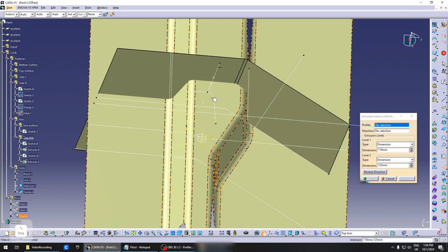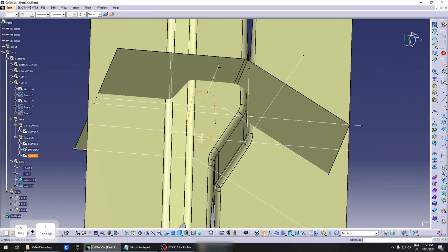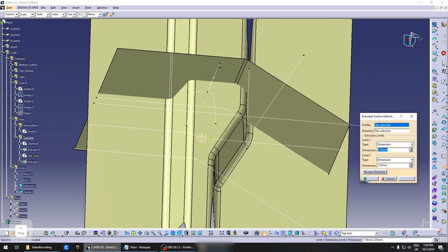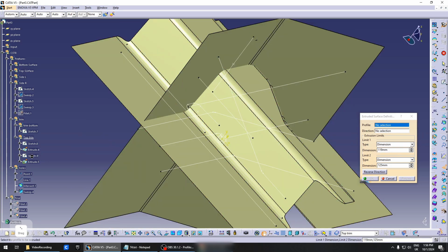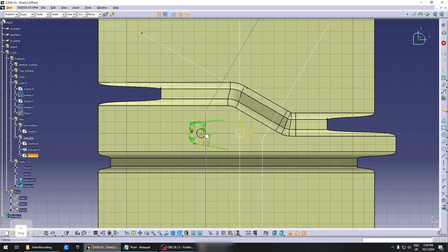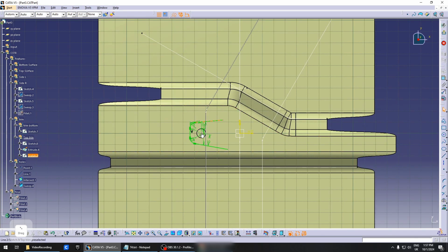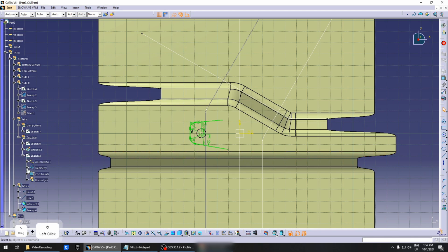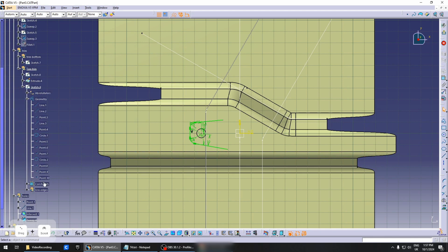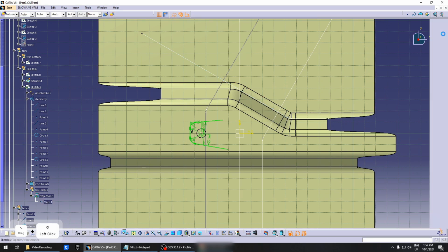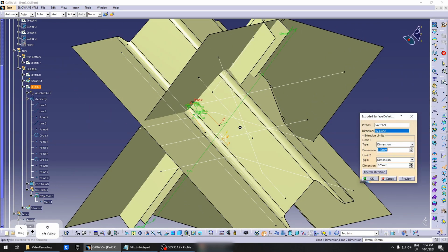Good. We can go ahead and extrude this. It doesn't like the fact that this is not a construction point. Looks like I didn't make it a construction point. You can go here to user edges and click this point that you have projected and make this a construction point like that. Good.